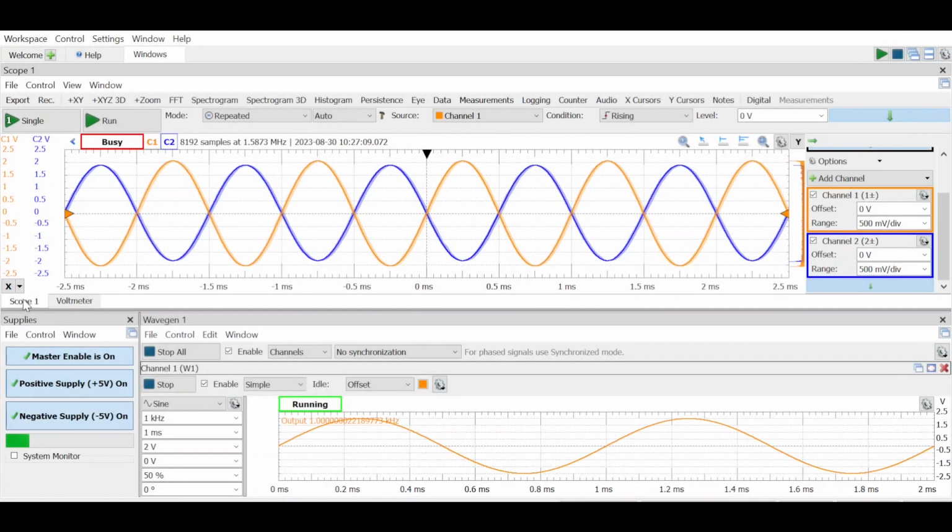As we conclude, I hope you'll never forget that the input impedance is very different between the inverting and non-inverting op-amp. In many applications, you would be better off using the non-inverting input because it has a higher input impedance, which is to say it's less likely to load down your circuit, resulting in better performance.